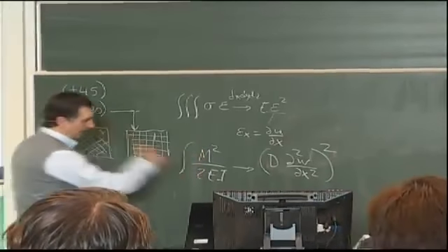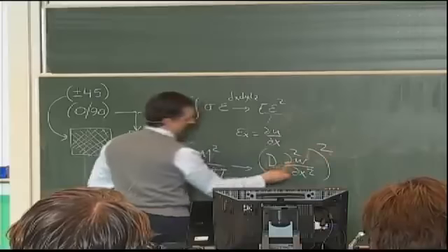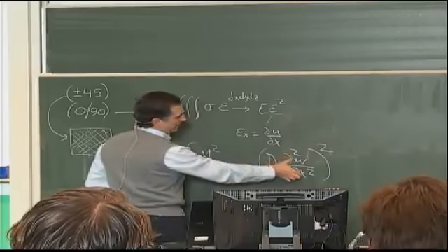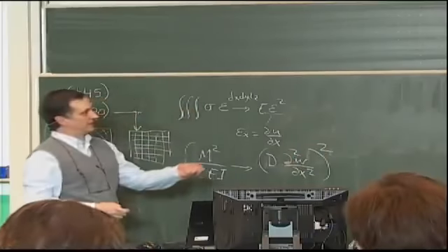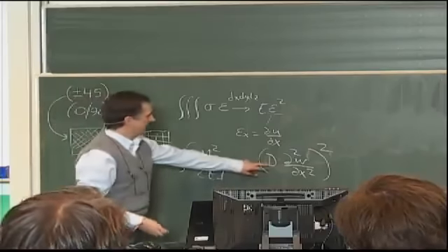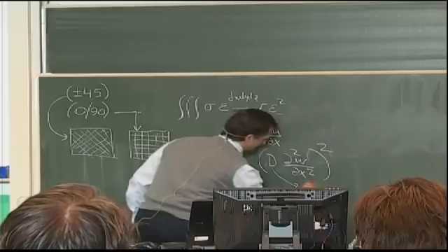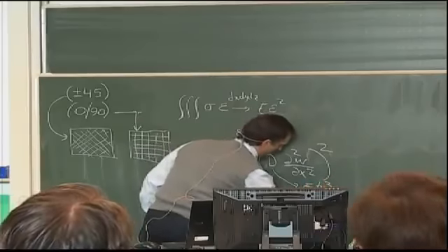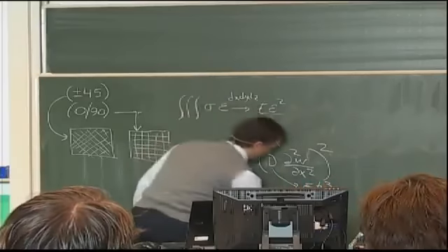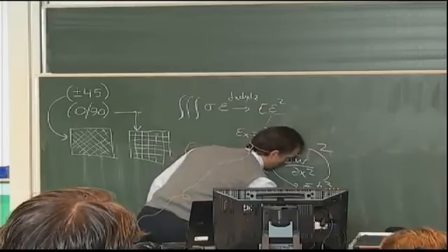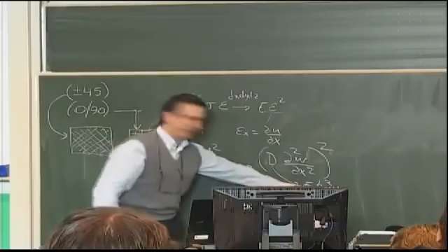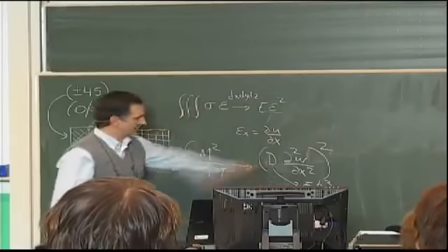In anisotropic, I would expect to have terms like this, which means I have the second derivatives of w squared, which you can see are there. And then I have a D, which in an isotropic material is E h cubed, the thickness of the plate, over 12 times 1 minus nu squared. So if you're doing an isotropic material in bending, there is a term that will always appear, which is the D, the so-called D.